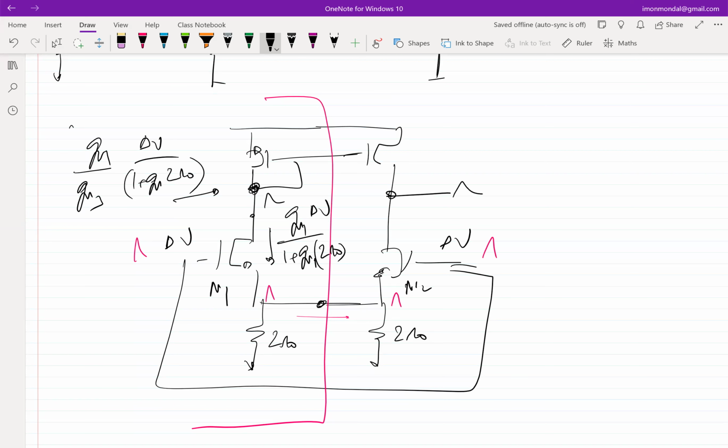So essentially, instead of this differential amplifier only responding to a differential input, it also responds to a common mode input. By common mode, I mean that both the inputs are going up and down at the same rate. So this is one of the metrics to characterize a differential amplifier: what is the common mode gain with respect to the differential gain, right? There is a technical term for it, but you don't have to bother. The technical term is CMRR.